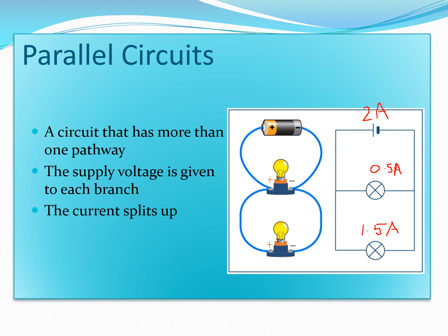So, just to finish there, difference between series and parallel. Series circuits have 1 path, parallel have more than 1 path. Voltage splits up in a series circuit, doesn't split up in a parallel. Current doesn't split up in a series circuit, does split up in a parallel.